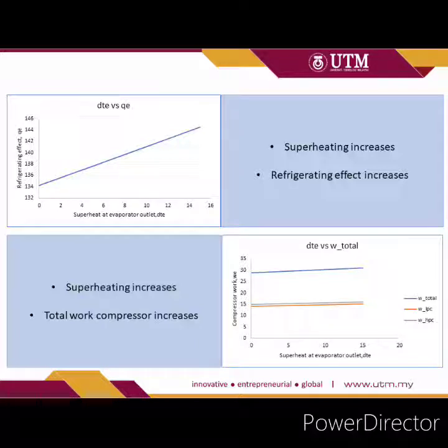When we increase the superheating, the refrigerating effect also increases. Next, we go to the second graph, which is superheating versus total compressor work. As we increase the superheating, the total compressor work increases. This is because the work of the low pressure compressor and high pressure compressor both increase.